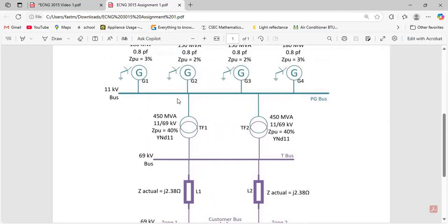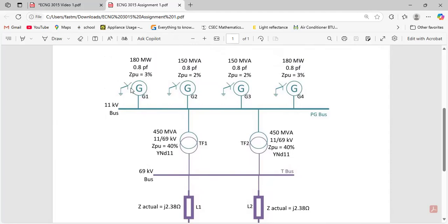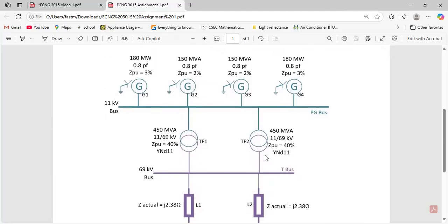So the purpose of the per unit system is basically just to standardize the entire network. Once you standardize the entire network to one MVA base and one voltage base, it will make calculations easier because you'll be dealing with basic ratios. So 50 MVA will always be 5, no matter where you are on the network. If you operate everything at different MVA bases and you change something here, you have to redo the calculation here and everywhere else on the network. And you don't really have time to do all that.